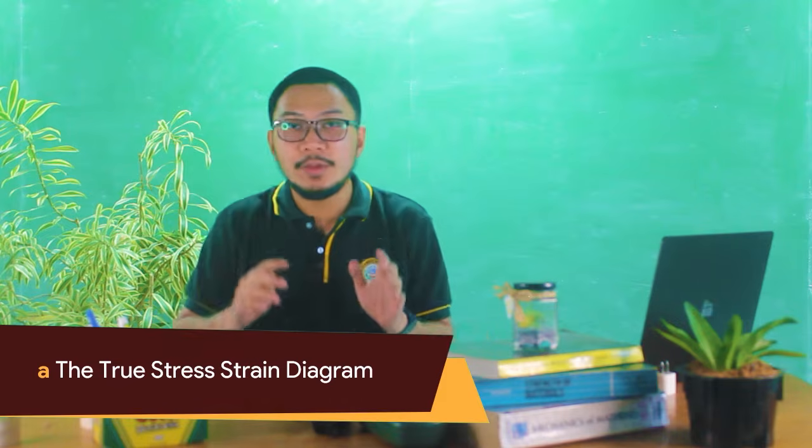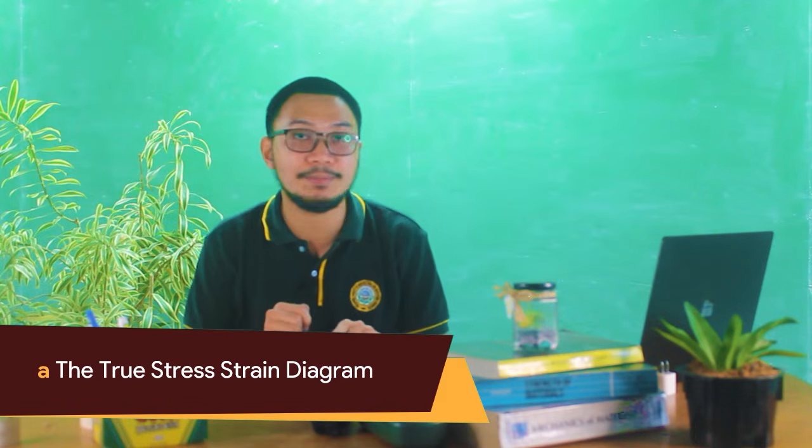Okay? And especially this modulus of elasticity, importante kaayo ni. Kaya atong gamiton sunod. And again, this is your conventional stress-strain diagram, but if we are talking about true stress-strain diagram, we are now considering the cross-sectional area of the neck part.